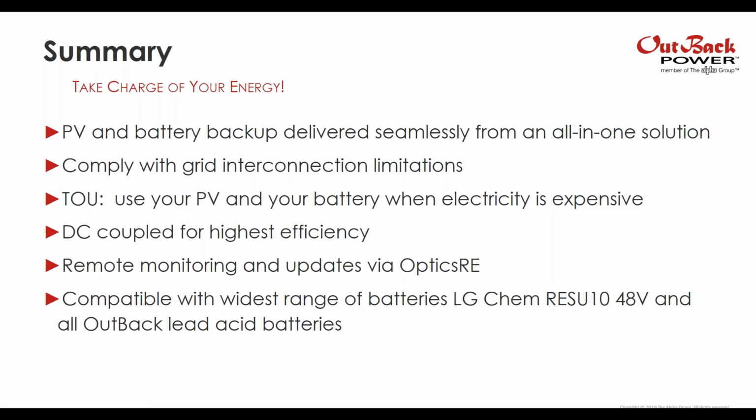So in summary, SkyBox allows you to take charge of your energy. PV and battery backup are delivered seamlessly from one single box solution. It totally complies with all grid interconnection limitations or requirements, so it's California Rule 21, HECO 14H compliant. It enables time of use, so you can use your PV and your battery when electricity rates are high.